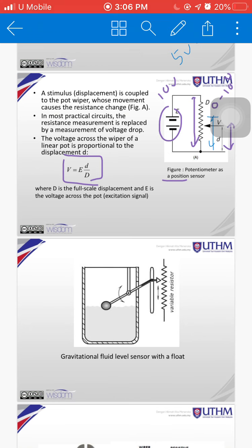The main element is a float, which is a device that has a density lower than water. In most tanks, it is directly coupled to a water valve to keep it either open or shut, depending on how much water the tank holds. So the float is a detector of the position of the water surface. For the measurement purpose, the float can be coupled to a position transducer such as potentiometric, magnetic, capacitive, or any other sensor.